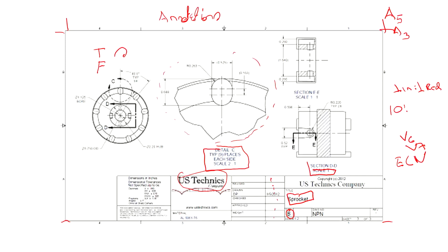documentation needed. Important stuff is for the manufacturing department to know if the tolerances are going to be standard or precise, or more unique standards, or if they're going to be custom tolerances. The units are also going to be displayed, and then obviously the drawing itself. So there's a minimal amount of data. You can put a lot of data, but there's just some basic stuff that is needed.